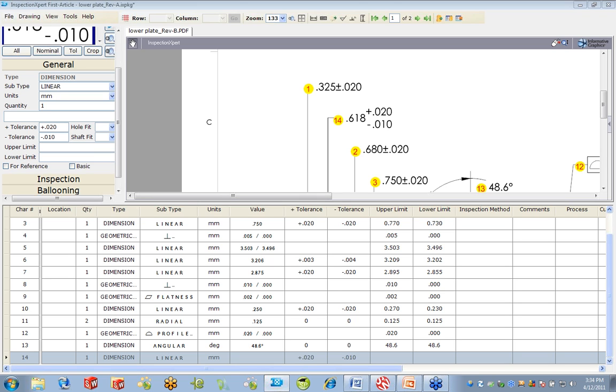It uses, like I said, optical character recognition to look at the image to figure out what you have. Now, when it comes to SolidWorks, if you're dealing with Inspection Expert for SolidWorks, as long as you're using SolidWorks dimensions, that's what it's going to extract. There's really no other way, right? You're either dimensioning it in SOLIDWORKS or you're not dimensioning it at all.